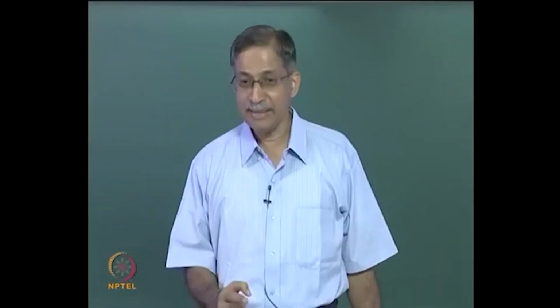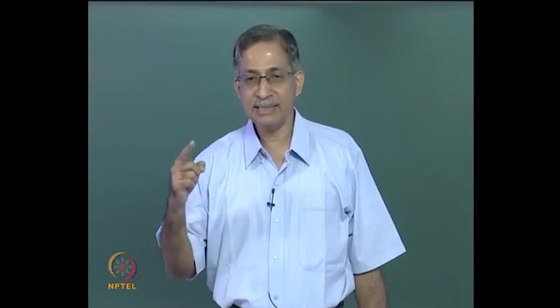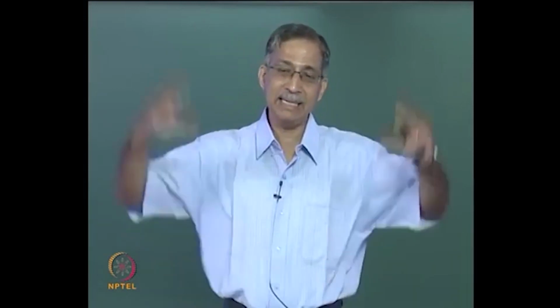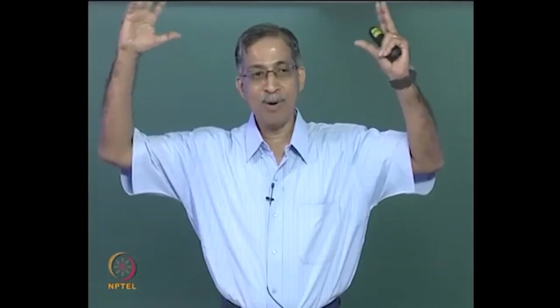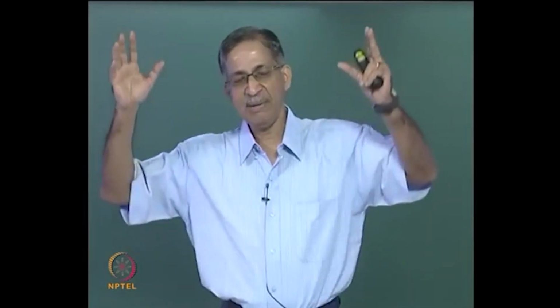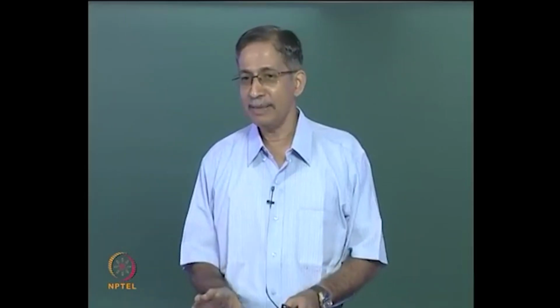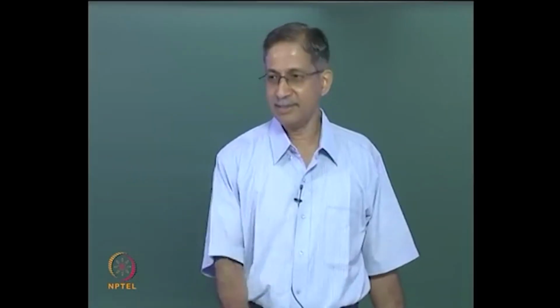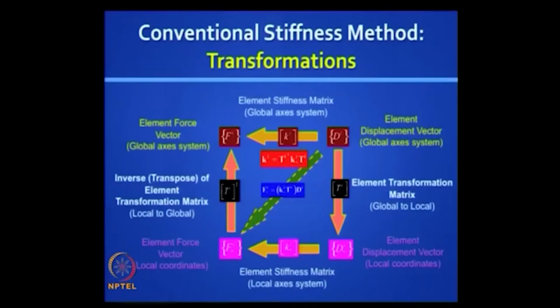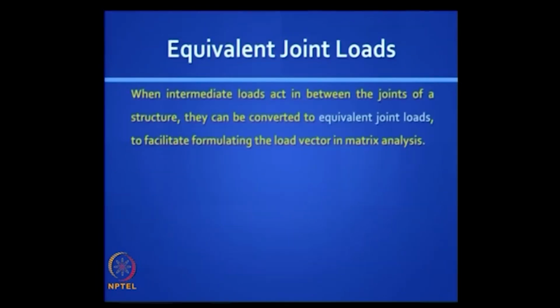There is another method called using the displacement transformation matrix, where you directly deal with all the global coordinates in one go, but you will be dealing with big matrices. We will show both, but when you are doing programming, you are dealing with large structures, this is the way to do it. Okay. In your examination you have the choice, whichever you like you can do, but whenever possible do not do the conventional stiffness method, use the reduced element stiffness method. You deal with much smaller matrices, you can finish the problem much faster.